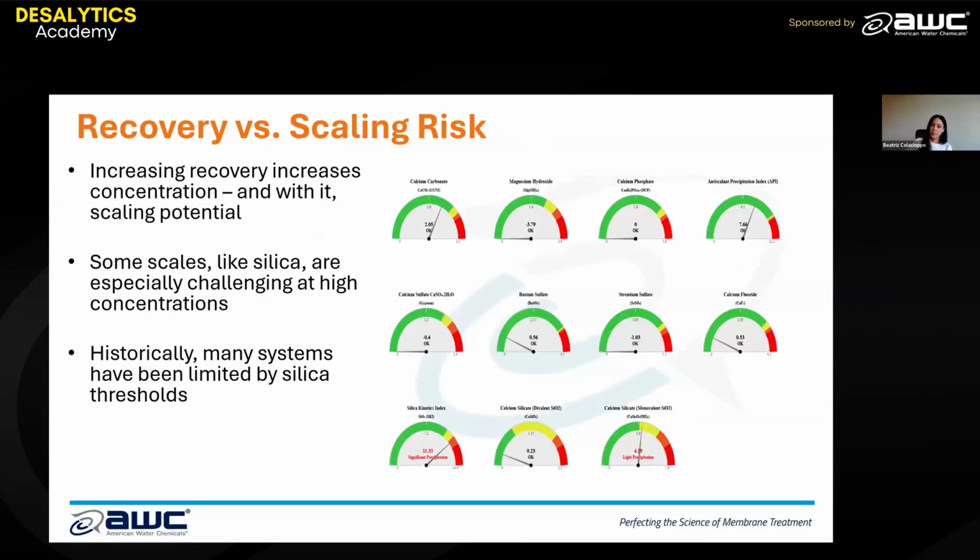One comment I do want to make here is about recovery, because there is a big push across the industry to increase recovery, maximize as much of the water recovery you can have and minimize that waste of the reject stream. The problem is, every time you're pushing the system harder, you're also pushing the chemistry to its limits. So as we concentrate the water more, we have more things reaching the saturation limits or even going beyond, and the scaling risks increase.